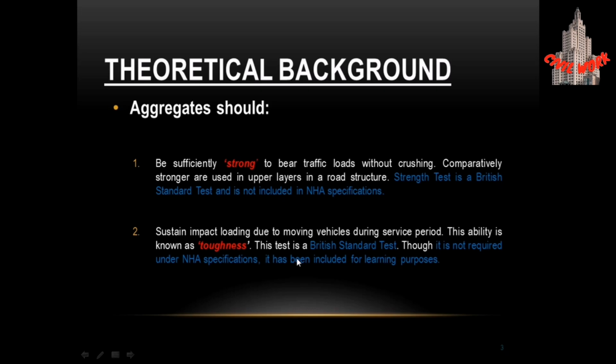Now we need a clear view of what hardness is and what toughness is. Hardness is generally related to surface resistance, while toughness focuses on bulk resistance. Hardness measures resistance to indentation, while toughness measures resistance to fracture. Lastly, hardness is typically measured under static loads, while toughness is measured under dynamic loads, which is also known as impact.